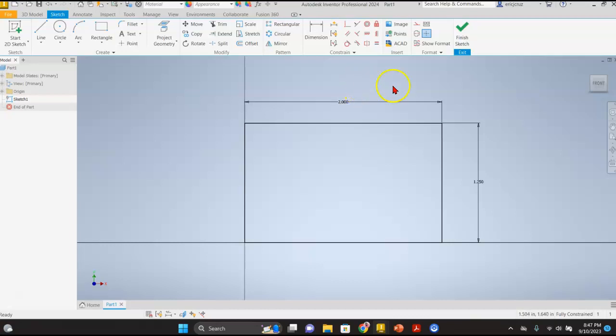Now let's get in the good habit of keeping our mouse in our right hand and our left hand on our keyboard so that we can quickly tap the escape key or other keyboard shortcuts. Like for example, if I press D on the keyboard, I highlight dimension. If I press C on the keyboard, let me tap escape. If I press C on the keyboard, nothing's happening. Which one is it then? Oh, it's Control Shift C. L, we'll start the line tool. There you go. Okay. So some tools are easily accessible with the keyboard, and we'll learn those as we go.